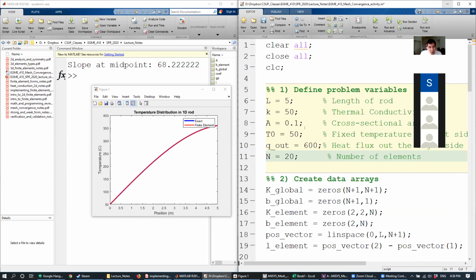If it's not really converging, you're changing gradually and it's not plateauing, you can speed up the increase until you basically see that. Then you can go back and fill in some extra points. The thought process is to start gradually. But if you don't see much change, or you still see it changing quite a bit, then you can ramp up how quickly you refine it, so you can reach convergence a little bit faster.